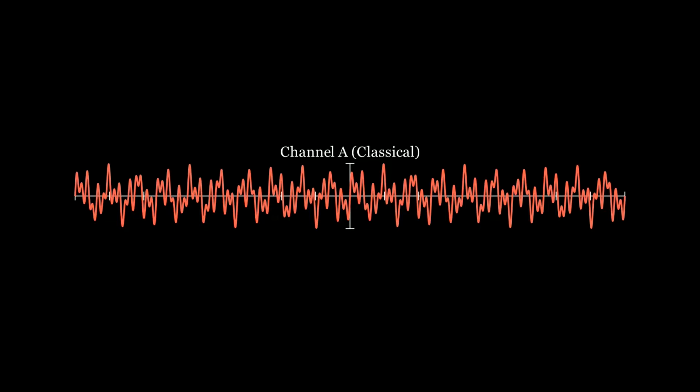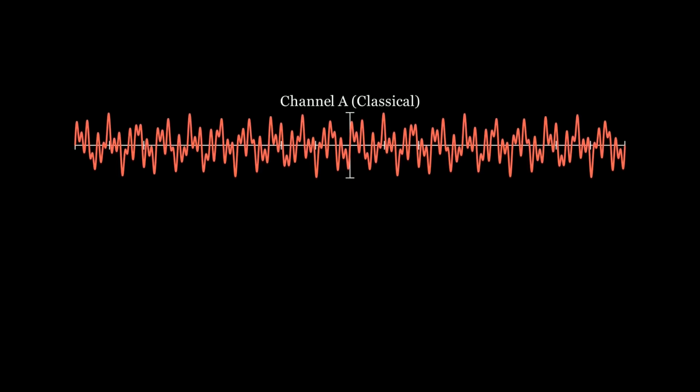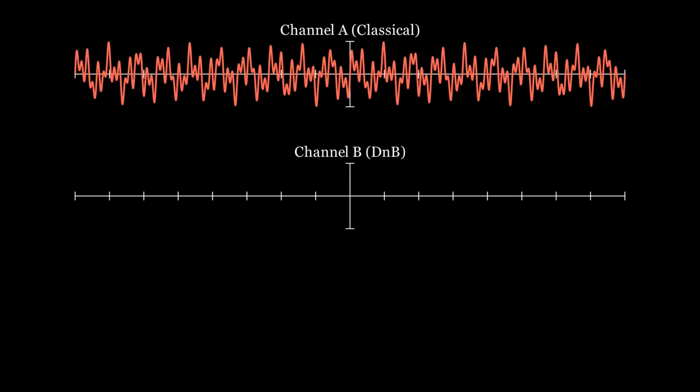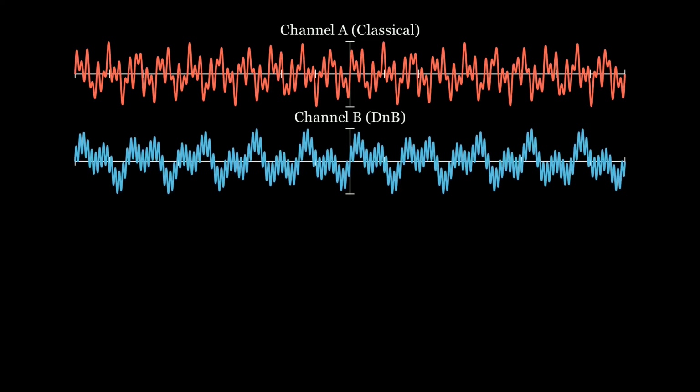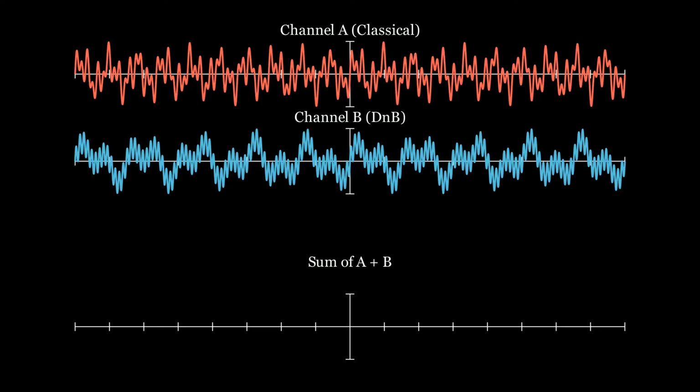They broadcast by channeling the raw audio waveforms from the music directly into their broadcast antenna. Everyone in the area can listen by channeling the raw signal from their radio antennas directly into their speakers. This system works alright until another channel, which we'll refer to as Channel B, decides to debut their selection of recent D&B hits. Channel B broadcasts using the same method as Channel A, but the signals effectively sum in the air, and the listeners receive the combination of both signals.